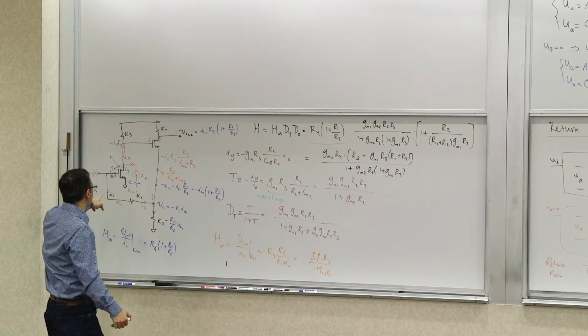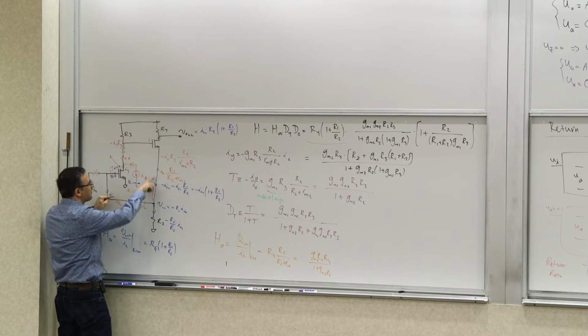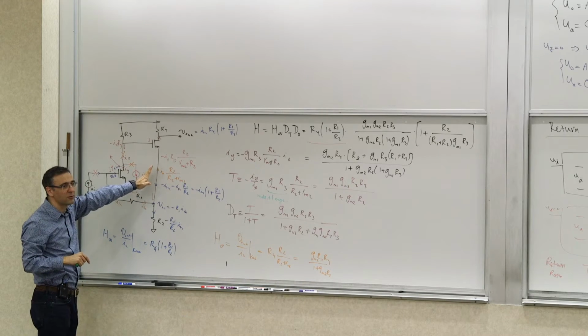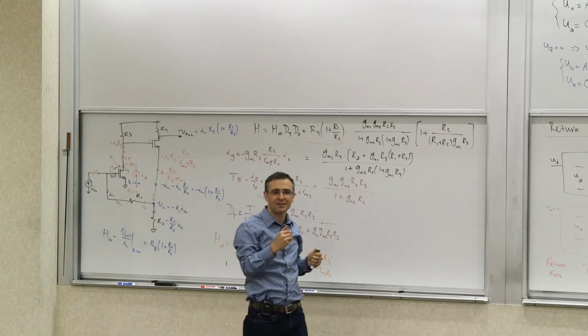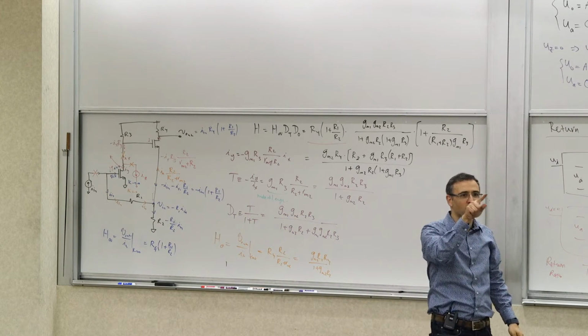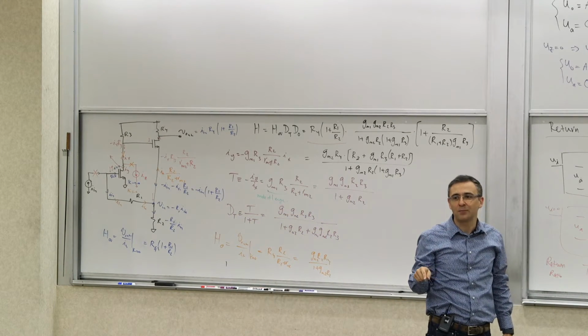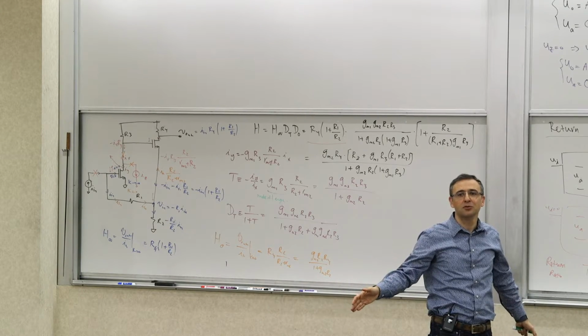And in fact, this is interesting, because sometimes this feed forward through this direct forward transfer can produce an overshoot in your response. If you have capacitors and all those things, you can be in a situation where you see an overshoot and say, oh, my circuit is underdamped, something like that. It may have nothing to do with that.